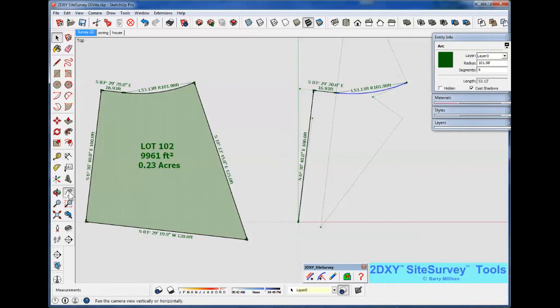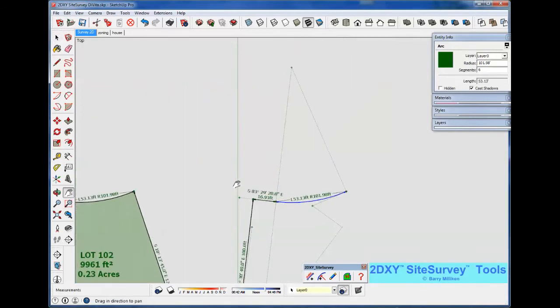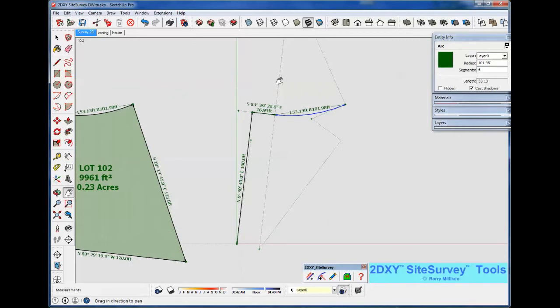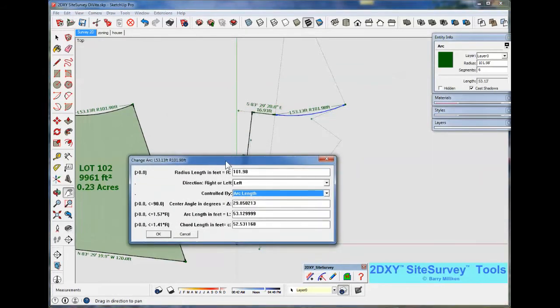And if we move the screen a little bit, you'll see the center is way up to the north there. There's a new guide showing where the new tangent line would be for the next bearing or arc. And we can proceed to draw this next bearing. So this arc is selected. Just as an illustration, I'll show you what another arc tangent to this would look like.